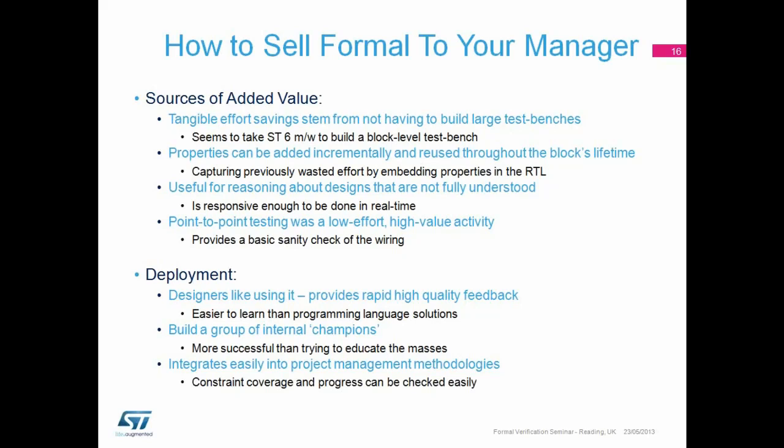Whenever we do block level verification at ST, it always takes us 6 man-weeks to build a block level test bench. It normally goes the same way. The verification engineer gets the spec, reads the spec for a week, puts it to one side. Week 2, has a fiddle, maybe designs the test bench. Week 3, starts implementing some UVM-based test bench. Week 4, tracking bugs. Week 5, it's just about hitting maturity. Week 6, you can start actually finding bugs in the design.